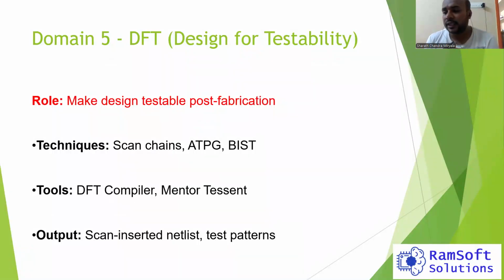The motto of design for testability is that you need to make chips that are testable after the fab, after the fabrication. That may include inserting scan chains for testing internal nodes, generating test patterns using ATPG, and adding built-in self-test circuits, that is BIST circuits, inside the chip.